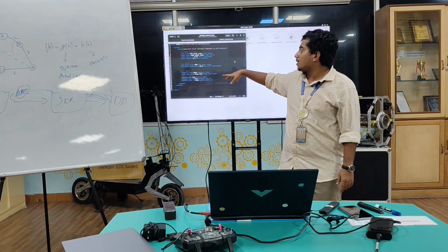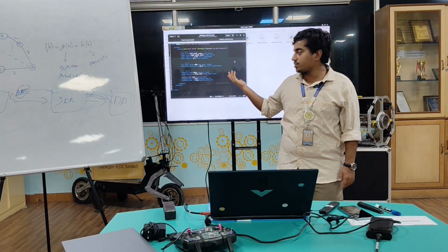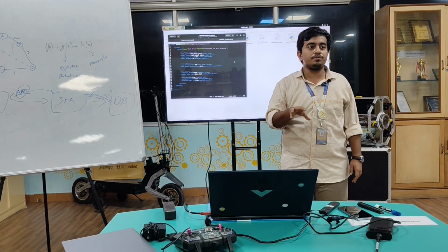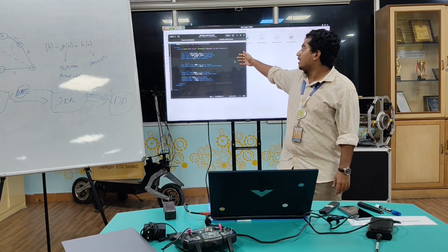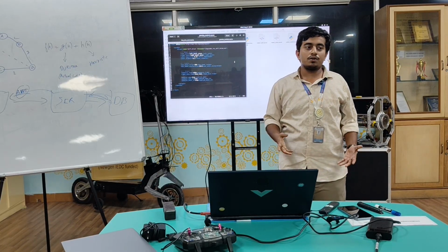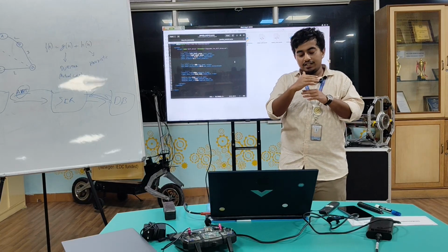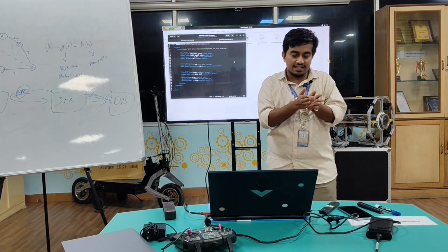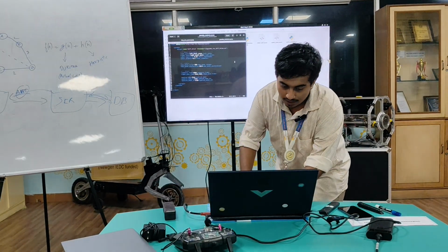This is how the design of our system looks in ROS. To deploy your system in ROS, you have to use a URDF file, but you may ask why this is Xacro. Xacro is built on URDF, and it helps us segregate the URDF files and combine them together.